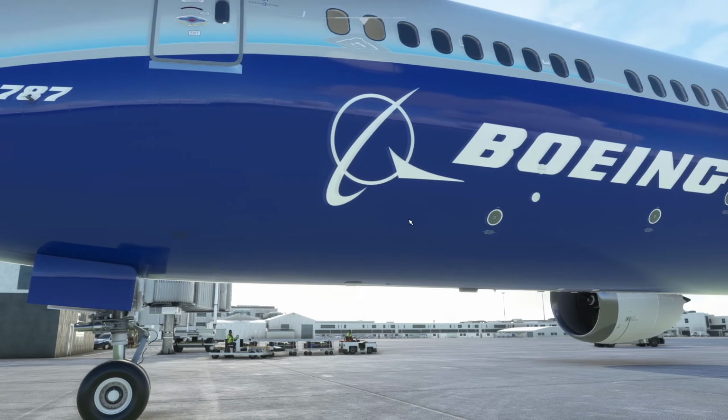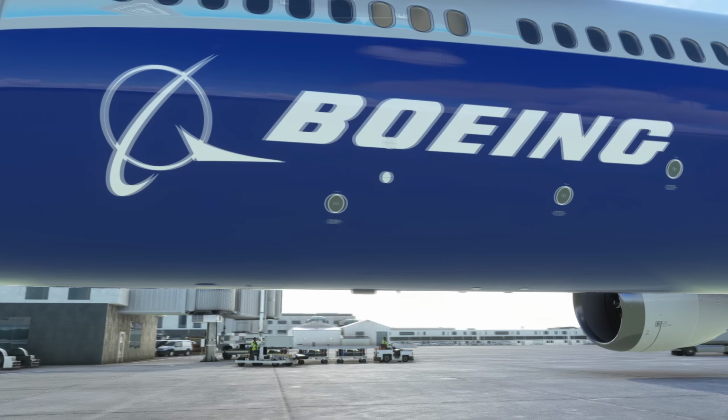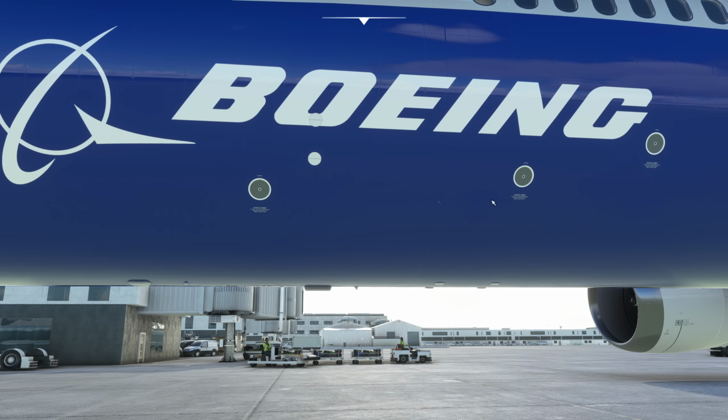And you can first start off by looking down the side here, and we have these static ports. There's 3, they're spaced out quite far, and then there's another 3 on the other side. The air data system on the 787 is, of course, as we would expect, different to most airliners. These static ports all feed into one system that then chooses what it thinks is the correct data. That's something we'll come to later, but it's not such a direct system as this is the captain's, this is the standby, this is the FO.